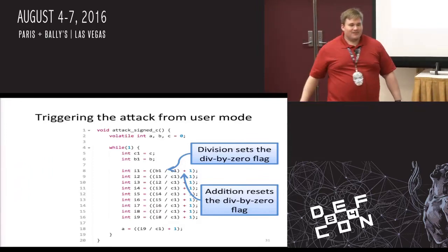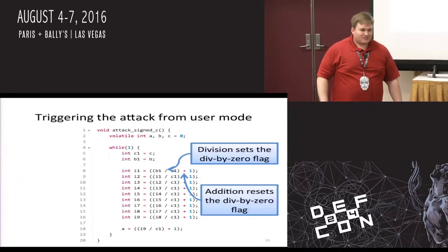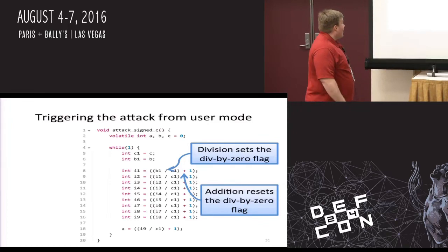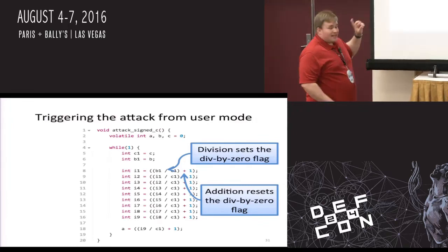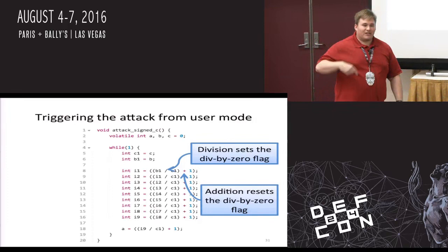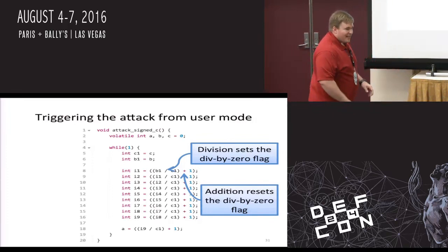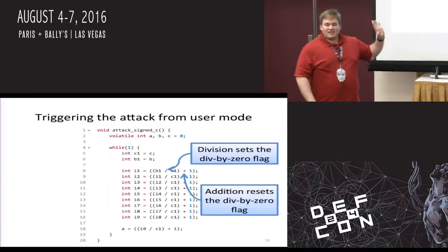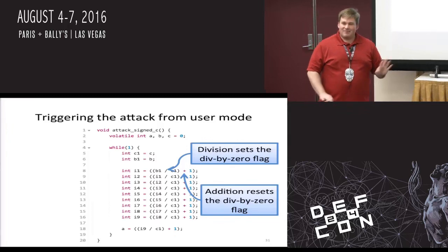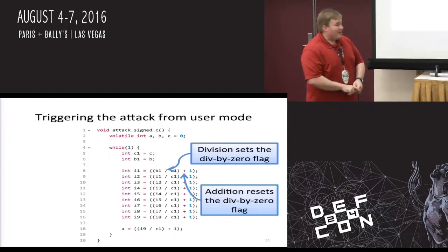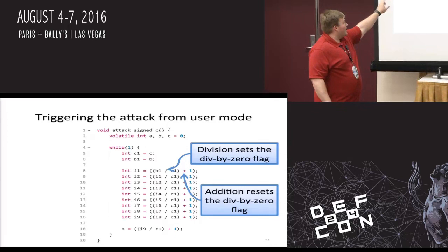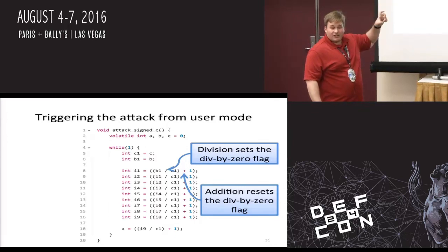Oh yeah, questions are awesome. Why use C1 here? Why can't you just use C? So you can't use C because the volatile means it'll have to read that register every time. Don't worry about this too much. I played tricks with volatile, and the embedded people might know. But I wanted an initial read of that C. I want to separate those A, B, and C off to be different registers.